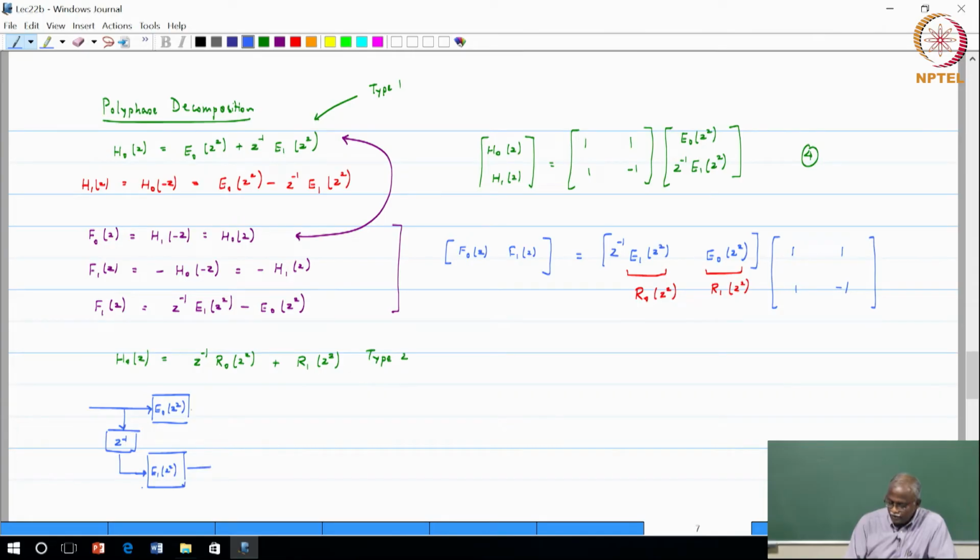Now comes the 2 by 2 DFT butterfly, basically the crisscross operation. The lower branch comes with a minus 1, with all the arrows moving to the right. The lower branch alone comes with a multiplication of minus 1, okay, outputs, and here you would have the downsampling by a factor of 2.